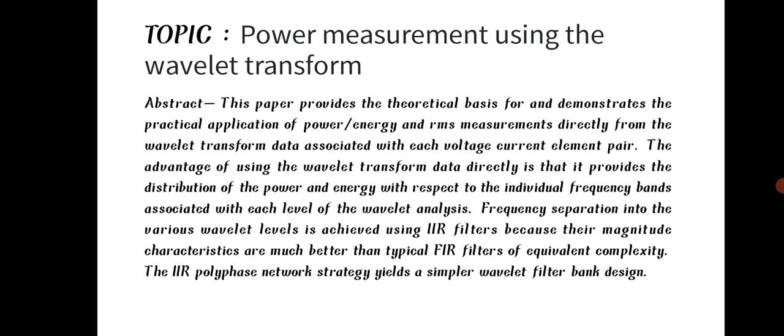The advantage of using the wavelet transform data directly is that it provides the distribution of the power and energy with respect to the individual frequency bands associated with each level of wavelet analysis.